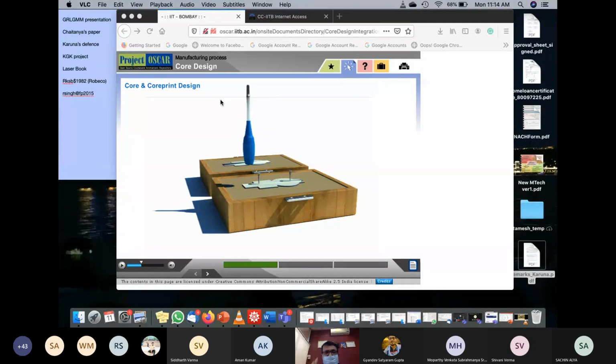So this plunger does two things. Once, it pushes the material to fill the mold. Number two, when it solidifies, it pushes it out of the mold, because the mold is a two-piece thing. Can you visualize that or no? Okay. So it just gets out of the mold when it's pushed out. So it will initially push to make sure that the mold is full, right? And once it solidifies, it will push it further, so that it comes out from one half of the mold. The other half, there can be push pins which will push the product out. Because you have to open the mold, right?